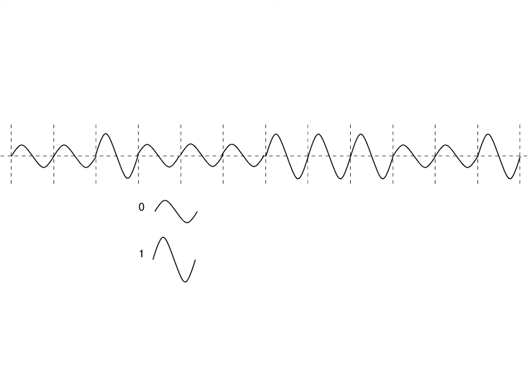And the definition of frequency is how many repetitions per second. You see in 2 milliseconds we have one. In the next two, another one repetition, one cycle. So in 1 second, we'd have 500 cycles. So our frequency is in fact 500 hertz in this example. And we can say the phase in both cases is 0, because we just follow the normal shape of the sine wave.